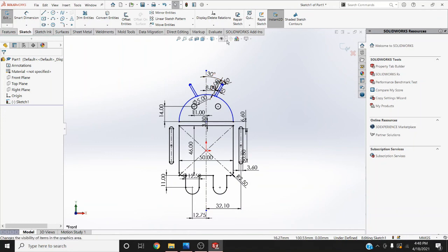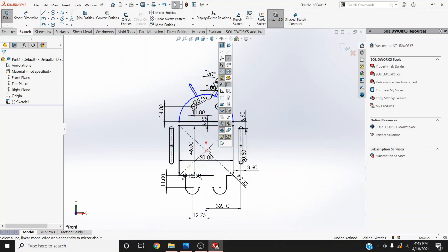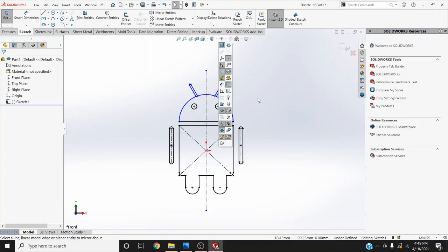If you keep seeing your relationships, what you can do, you can drop down this arrow key right next to the eye and have this thing unchecked, because this thing would look like this. To have it cleared up, I have it unchecked like this. There you go. And we can click on where it said view sketch dimensions right here and get rid of the dimensions. Okay,